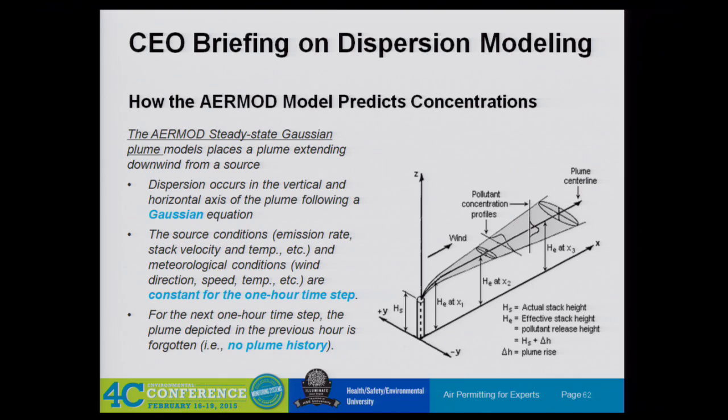Now, the last bullet there is each hourly model basically is independent of every other model. Some models will actually do this hour, then find out where the plume is, and then change the wind direction of the plume depending on how the wind migrates. This assumes that for the hours being permitted, the wind stays steady for the entire dispersion of the plume, even if it would have taken longer. So it doesn't move the plume around, but it does give each hour from the point source perspective. We're running this for each hour for 5 years. So that's why it crunches a lot of numbers.